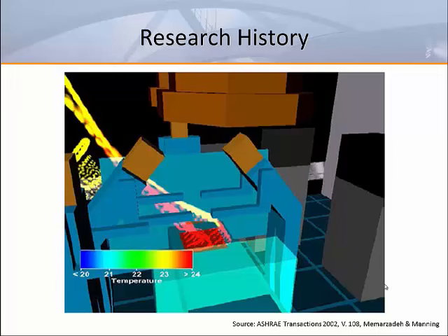of a thermal plume off the wound with a velocity between 25 and 35 feet per minute. Limiting the average velocity airflow above the operating table is intended to prevent the supply airflow from impinging on the thermal plume and potentially driving contaminants into the wound site.